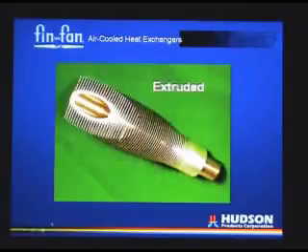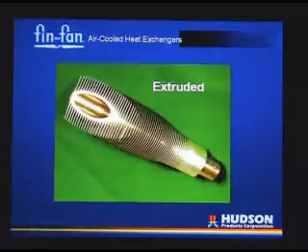You put a larger wall aluminum tube over the process tube. This could be either stainless, carbon steel, whatever you want, and then you take the aluminum and mechanically upset it so that you have an integral finned tube over the process heat transfer tube. This also has about a 20 to 22 area ratio between the bare area of the tube and the finned area.